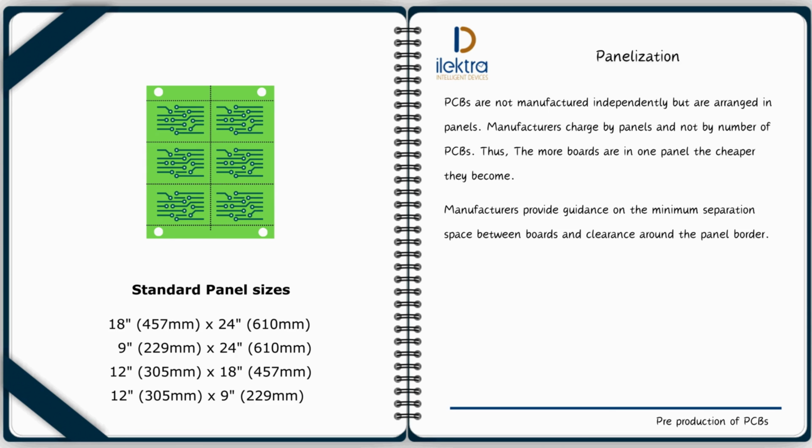Manufacturers provide guidance on the minimum separation space between boards and clearance around the panel border. The latter is necessary for panel handling and depends on the type of PCB. Multilayer boards usually require larger border clearances.